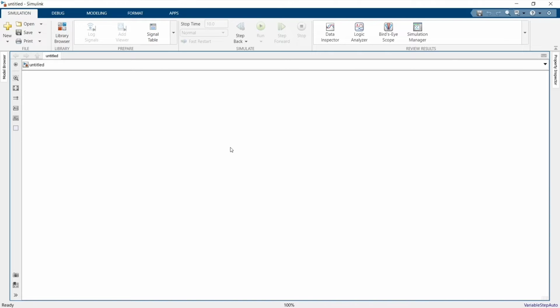I also need a gate or an IGBT to efficiently switch my circuit. Switching means it will switch on and switch off the boost converter depending on the power requirement. IGBT means insulated gate bipolar transistor, that is generally used for switching high power circuits where higher potential and high current is used. MOSFETs are used in low power circuits, in your small electronic devices. In larger, heavy electronic devices where more potential and current is used, we use IGBT for switching.